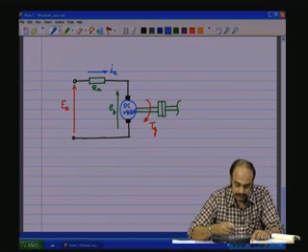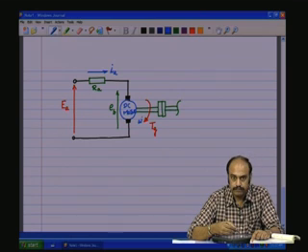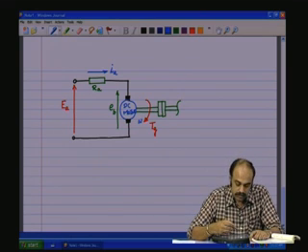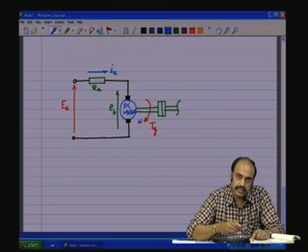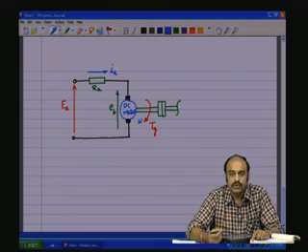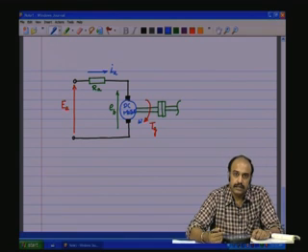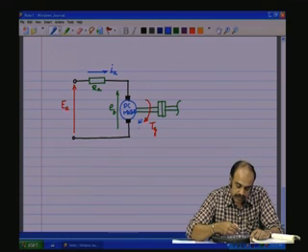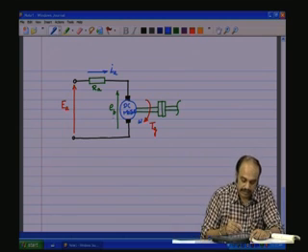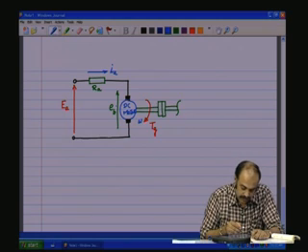If the speed omega reduces due to some reason like loading, then this will induce lesser voltage across the coils, because the induced voltage is given by P n phi z by 60. The induced EMF is proportional to n, the speed. So, reduction in the speed will cause reduced induced EMF, or the reduced back EMF, or reduced counter EMF. This is also called counter EMF in some of the literature.